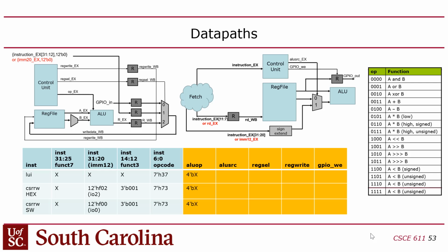Now, make sure in your control unit you drive the ALU-op even if you have these instructions come in, because you don't want to create a latch. If you don't set that, then the SystemVerilog is going to assume that it doesn't change, and so it's going to infer a memory there, right? And then when you go to synthesize this, it's going to go from a minute to 5 or 10 minutes, because the latches make it harder for the synthesizer to achieve timing closure.